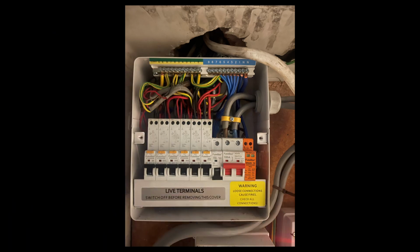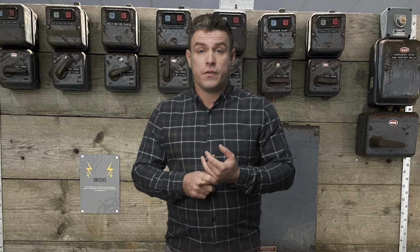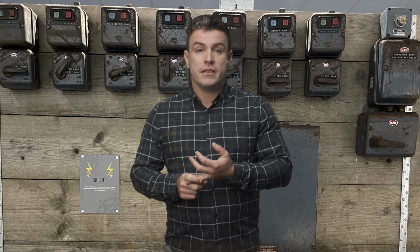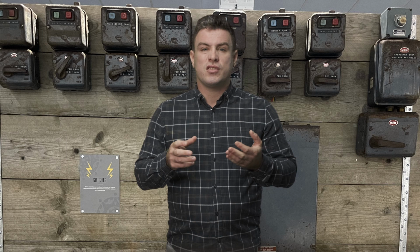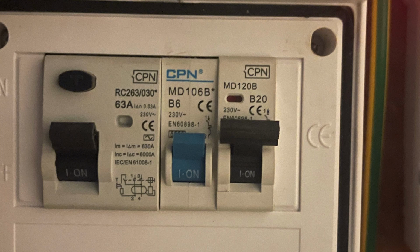I also looked at protective devices, which are designed to protect against earth faults and short circuits. These are the devices found in a consumer unit. Some factors that would be taken into account are the design current of the circuit or system, the disconnect time limitation, which will vary depending on the thermal trip, which tends to be slower, or a magnetic trip, the prospective short circuit current, which is the total path through the line, back to the transformer, and through the earth, and the rating of the protective device. It's no good using a 6 amp breaker for a ring main, is it? Plug in the kettle and it'll trip. A 30 amp or 32 amp would be far more applicable in this situation.